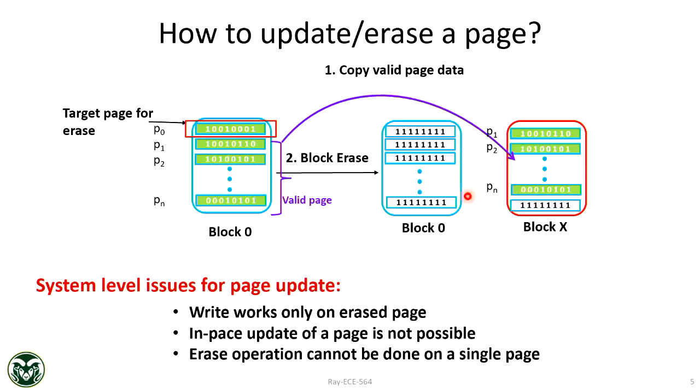What I'm showing is hardly done, because you cannot, just for a single page erase, write 900 pages on a new location. This will take a lot of time and a lot of energy as well. So you're asking if the data is just overwritten? Overwrite is not possible, because write works only on an erased page. Overwrite is not possible, which was there for DRAM or SRAM. You can update a page in place, so there was no erase command. But for NAND, unless a page is erased, you cannot write on it, and erase happens at an entire block level.